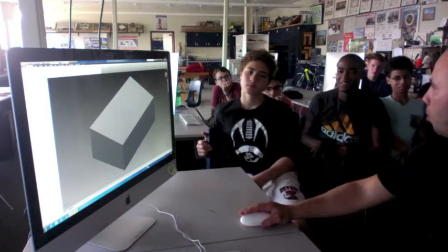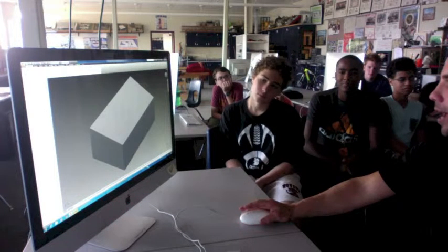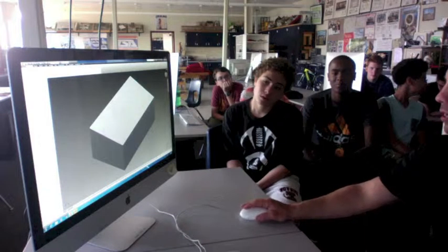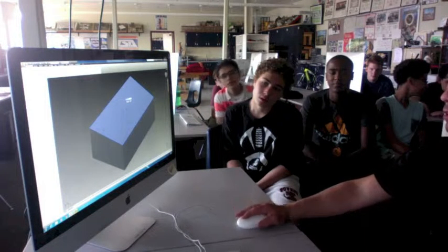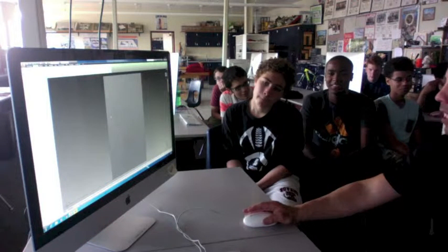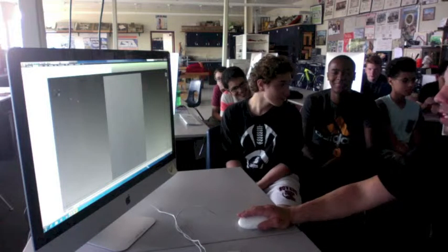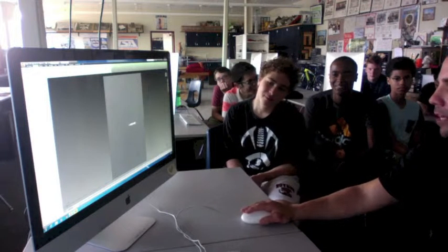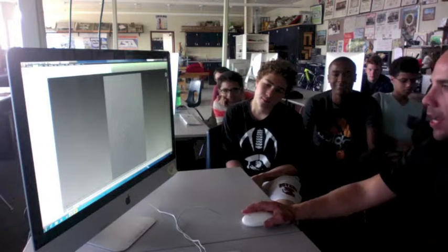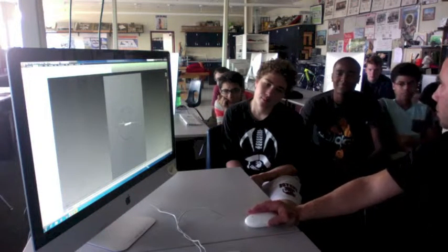And now I'm going to do the hole, right? I need a 1-inch hole in the center. How do I do that? I can simply go to Start 2D Sketch. Pick the top surface. And it puts me on the top surface, and I'm sketching that. Now, it knows where the center is, so I'm going to do a circle from the center point. I'm going to drag out, and I'm in input 1 for the diameter. Right? The diameter is the distance across the entire center. And I'm going to finish sketch.